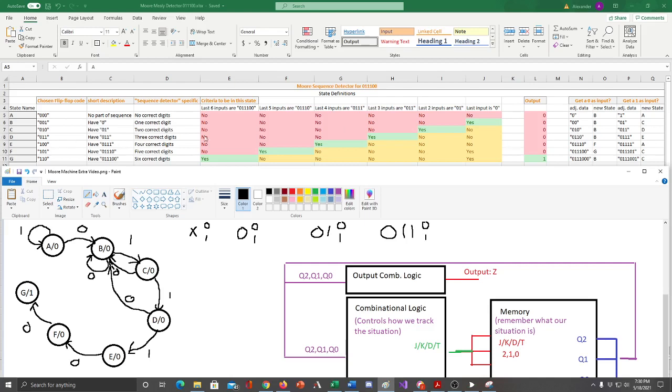Right? So state D, get an additional 0, it would be 0, 1, 1 followed by the 0. That takes us to B. On a 1, 0, 1, 1, 1 is the 4 match. That's the longest match that's possible. And so we would meet the 4 match, the criterion to be in state E, which is why a 1 in D takes us to E. So the process continues. I need the video to stay fairly short.